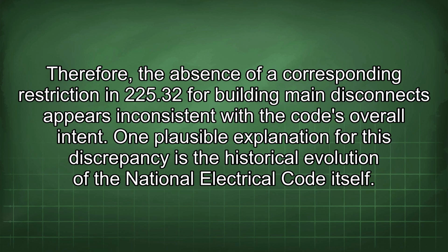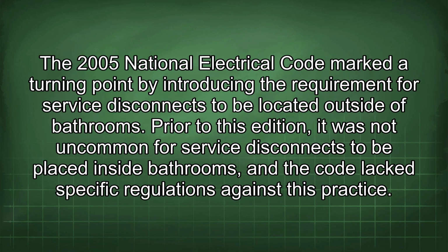One plausible explanation for this discrepancy is the historical evolution of the National Electrical Code itself. The 2005 National Electrical Code marked a turning point by introducing the requirement for service disconnects to be located outside of bathrooms. Prior to this edition, it was not uncommon for service disconnects to be placed inside bathrooms, and the code lacked specific regulations against this practice.